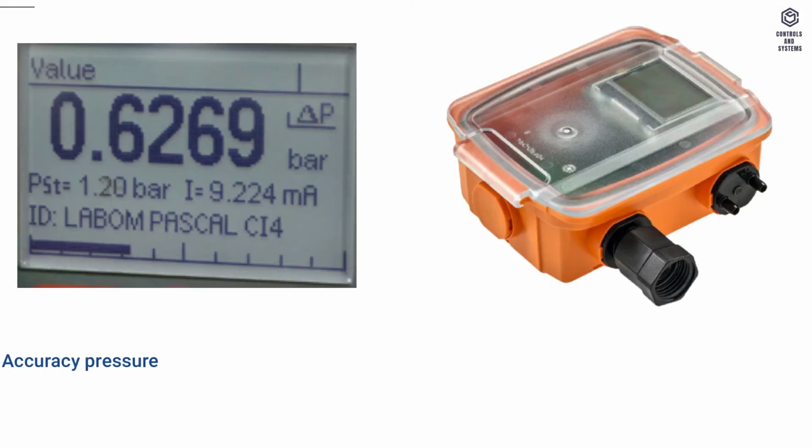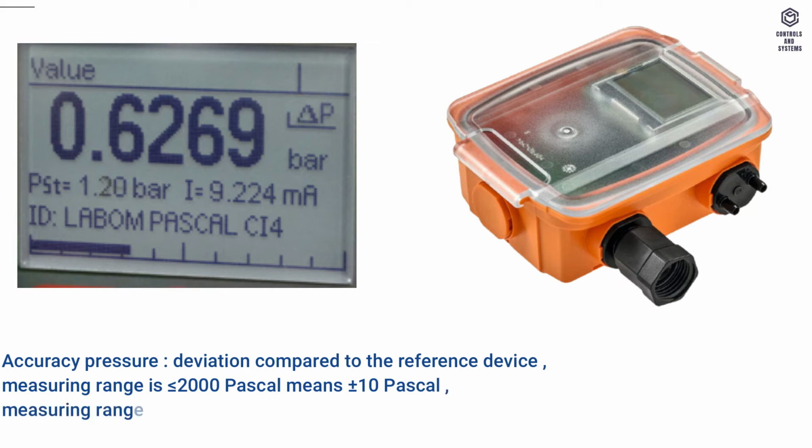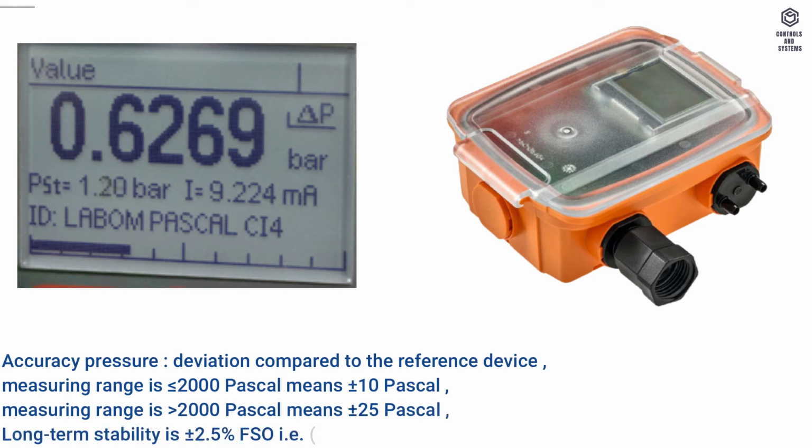Accuracy pressure, deviation compared to the reference device, measuring range is less than 2000 Pascal means plus or minus 10 Pascal, measuring range is greater than 2000 Pascal means plus or minus 25 Pascal, long-term stability is plus or minus 2.5% FSO, that is, full-scale output, for 4 years.